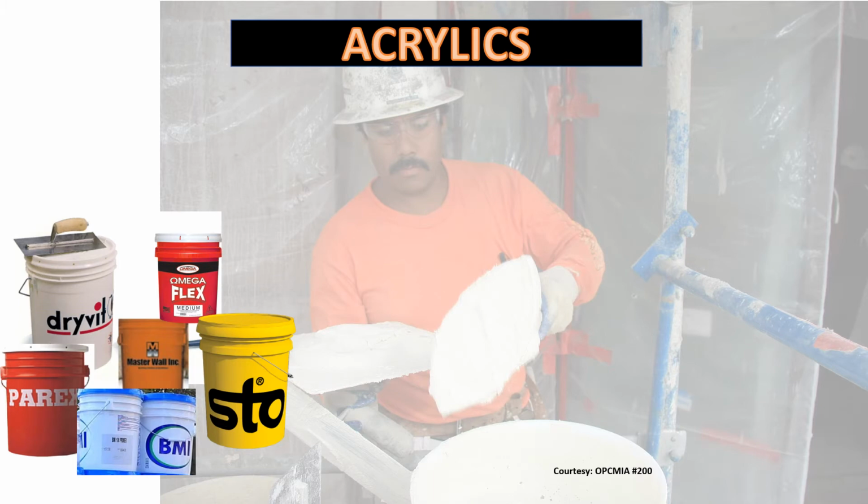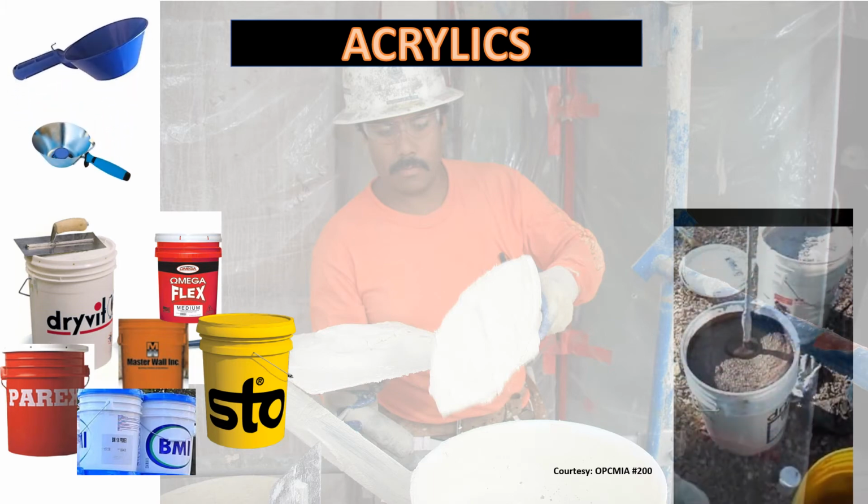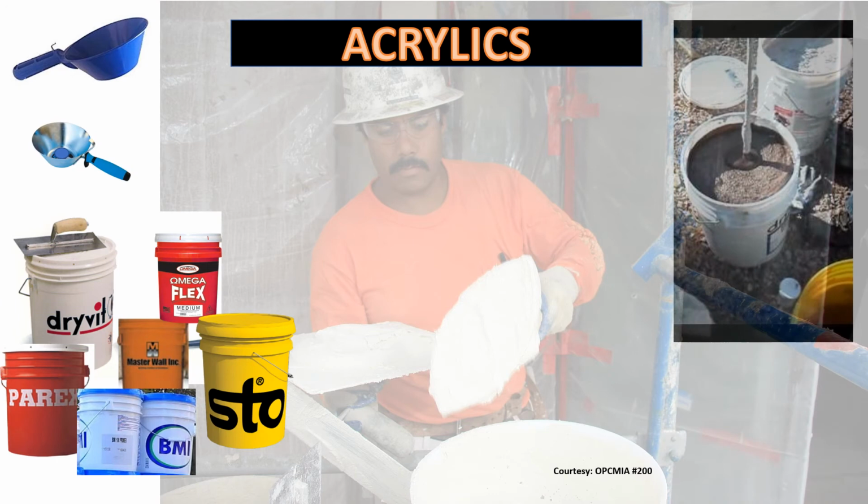Acrylic finishes are very popular today. They come in pails and need to be blended prior to application. They may be pre-pigmented or can have color added as it is blended on the job site. Some manufacturers allow small amounts of water to be added during this blending process. It is important to mix all the acrylic thoroughly. Even all the material at the base of the bucket must be mixed. Most plasterers take the acrylic finish directly from the bucket using what is called a scoop.